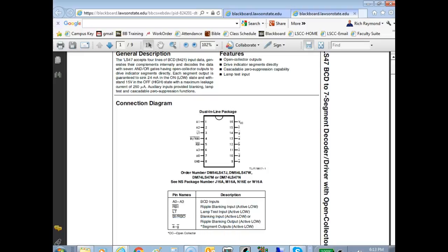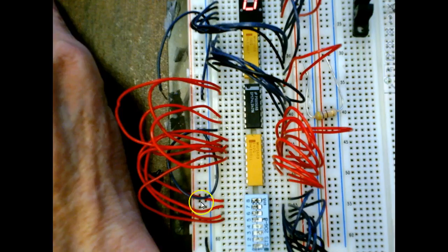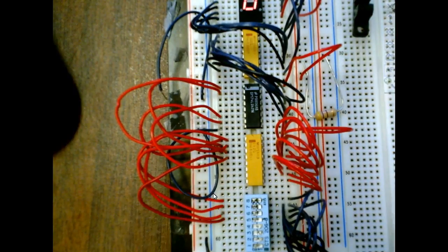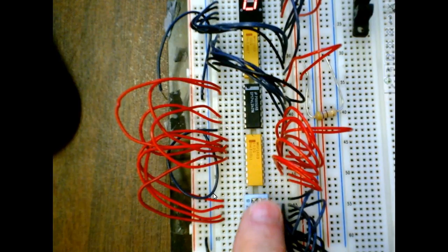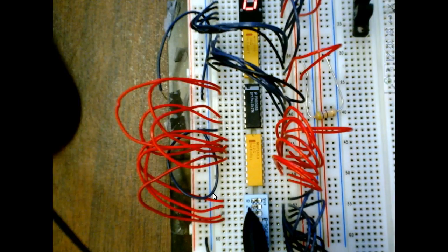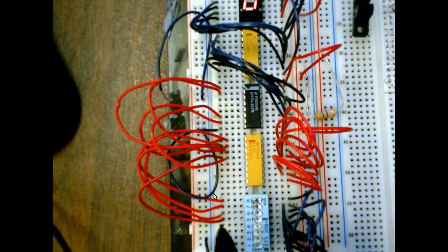By the way, we call these DIP switches. And why are they called DIP switches? Because they have the same spacing as a 14-pin DIP. So we call these DIP switches. And notice it's got 2 positions. It's got on and off. And by the way, you don't want to switch these things with a pencil because graphite is conductive and it'll get down inside the switch and cause problems. So you can say this has been switched with an ink pen quite often.